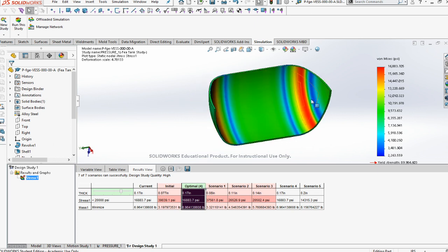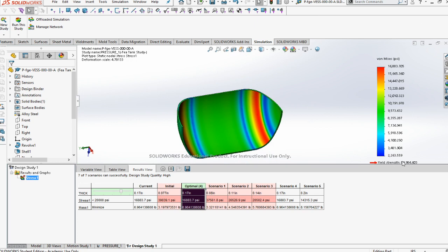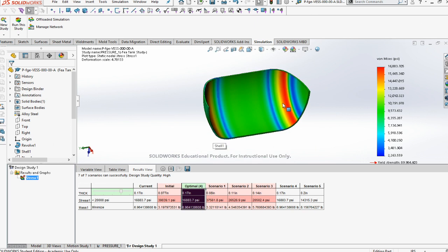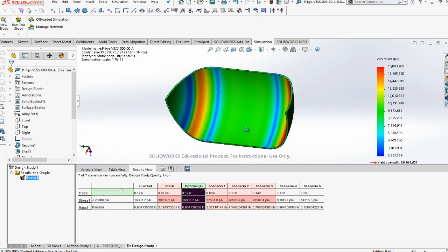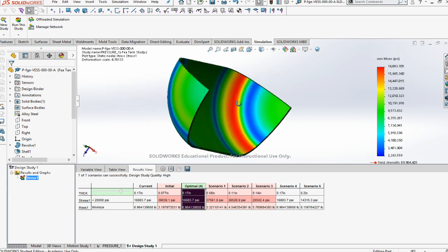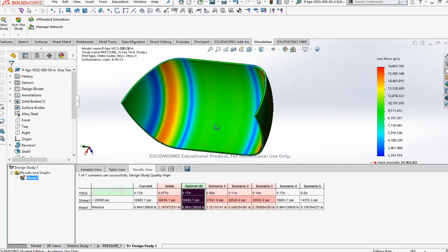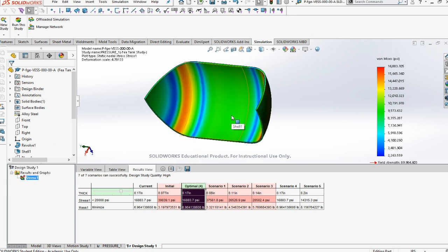So right now we're optimized with our model, and we optimize at a 89 is our yield. So right here we've optimized to a safety factor of about 5. And why different? Because you want to optimize something like this that's very dangerous. Instead of being a safety factor of 3, it's more like 5 on the design, because of the crazy mistakes that could happen. Alright, dropping out of a truck or anything like that. If somebody's just sitting out there and a kid knocks it off of a deck and it hits the backyard, you don't want it to explode or anything like that.